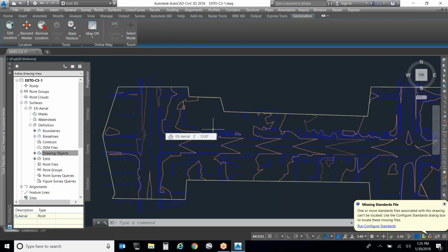All right, so we want to be sure that's kind of the overriding subject here: more than just the process of creating surfaces, but knowing how good they are and what they should be used for. And that data comes from the surveyor's survey notes, okay? In there is going to be the cover sheet in which they list which datum, which benchmark, which basis of bearings, okay?